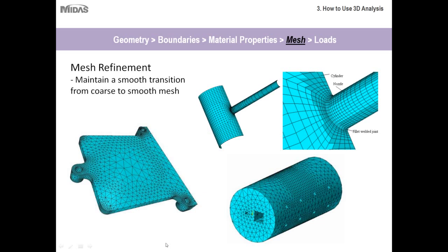Okay, and here's just some more examples of mesh refinement. As you can see, along these openings, excuse me, the mesh is much finer, because that's where you could reasonably expect the cracking and failure to occur. Whereas in the center here, not much happens, so the meshing is much coarser. This is all done for efficiency, so that your analysis doesn't run longer than it needs to. And then also along certain points here where we'd expect failure or cracking to occur, certain openings, entrant corners, etc., the mesh becomes finer.